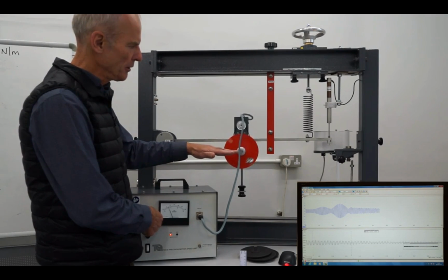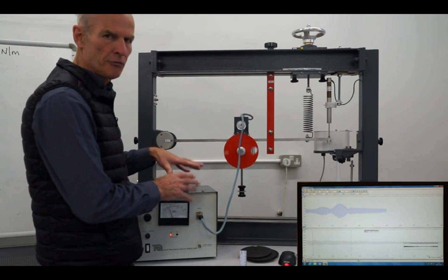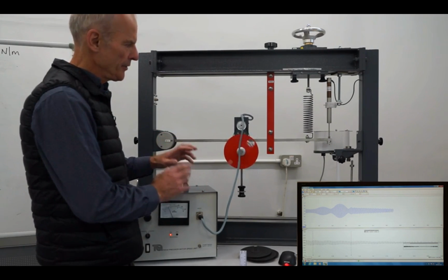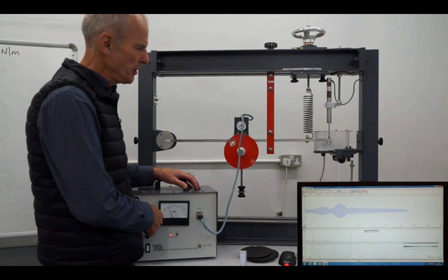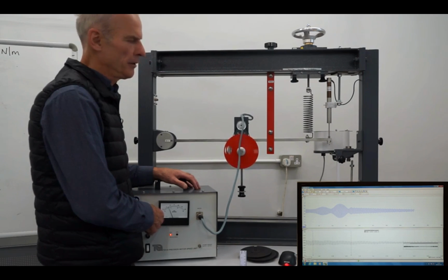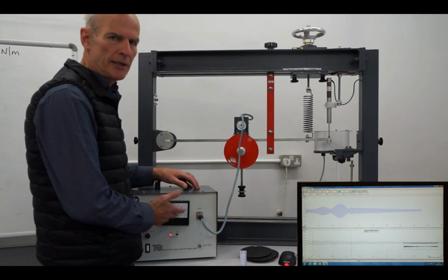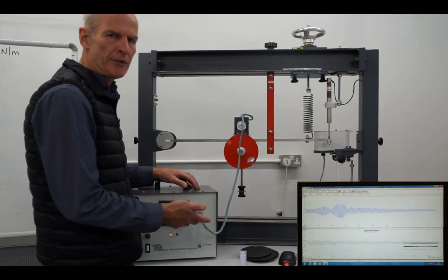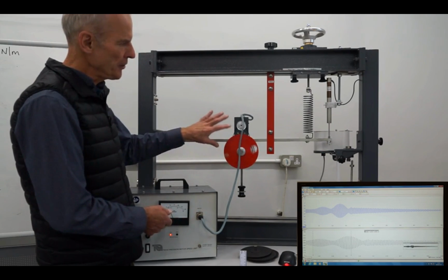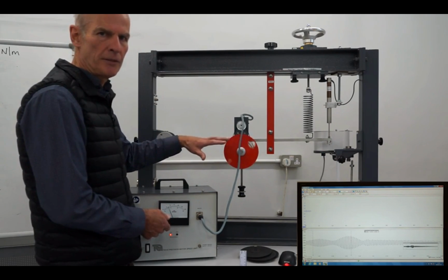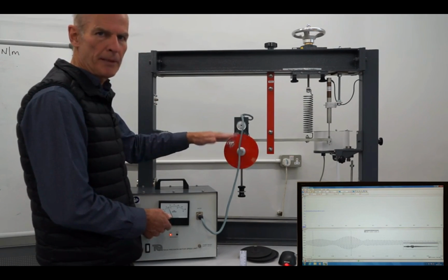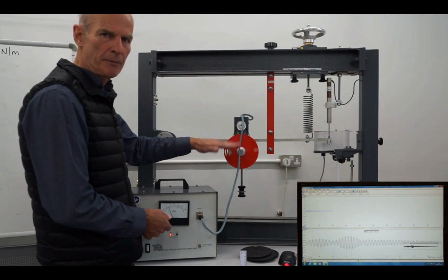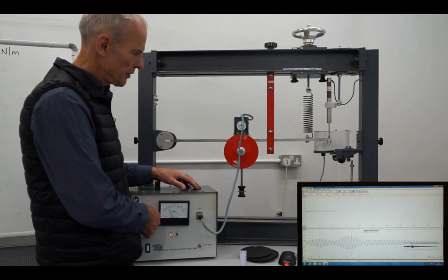The frequency which is vibrating is the frequency that you basically drive it at here. And that's always going to be the case. The issue though is what is the damaging frequency that you need to avoid, and that is basically large amplitude vibration or resonance is the theoretical one, but you never actually achieve resonance in a real system because you've got friction, but you can get close to it. So this is where this is going to vibrate a bit madly and it could damage the system, and this is something you need to avoid as a design criteria.